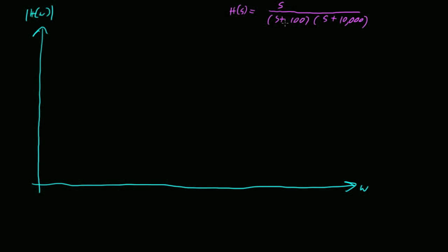Where's the first one of them? What comes first, the zero or one of the poles? The zero. Where is my zero? I have a zero at omega equals 0. So where is that on this graph? At the origin, infinite distance to the left. I'll give you a hint. This is a log scale.